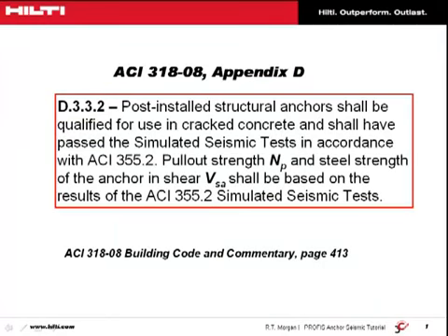Part D.3.3.2 states that post-installed structural anchors shall be qualified for use in cracked concrete and shall have passed the simulated seismic tests in accordance with the test standard known as ACI 355.2. When seismic design is selected as an option, PROFIS Anchor will perform calculations for both cast-in-place anchors as well as Hilti post-installed anchors.